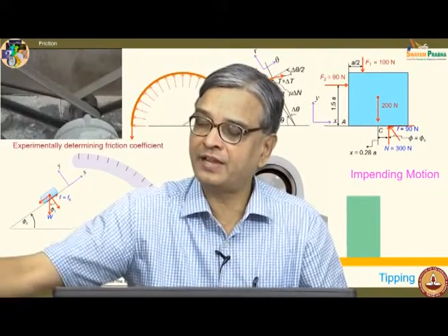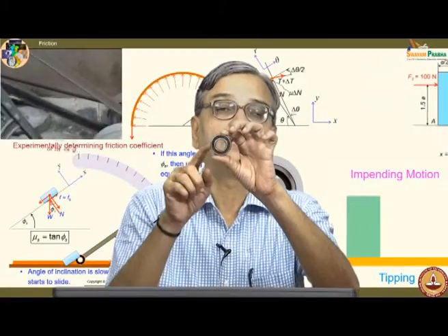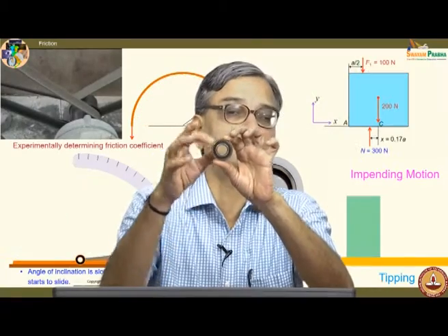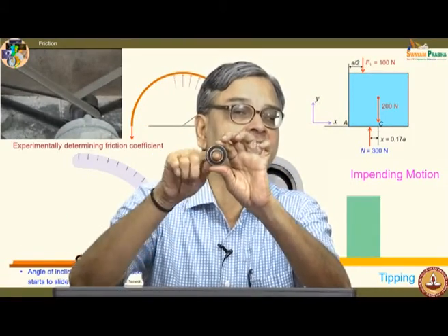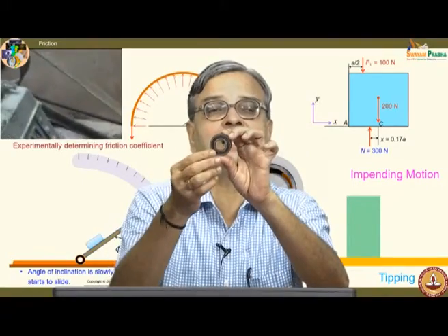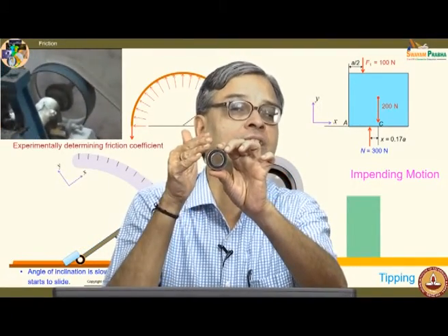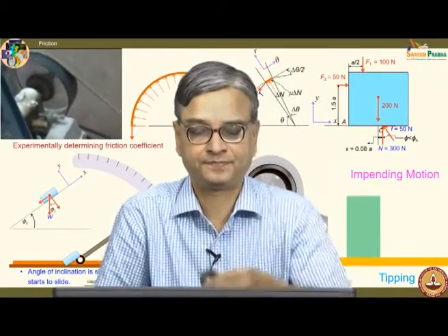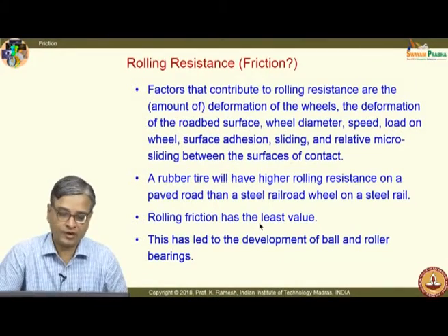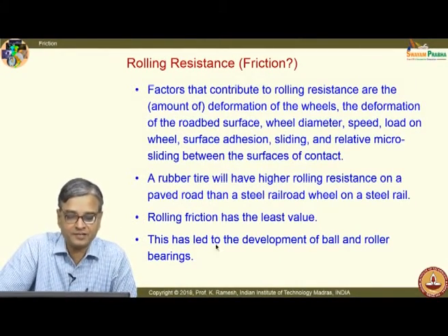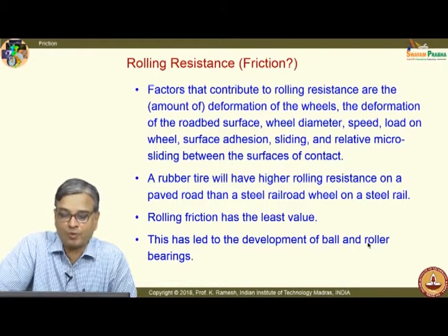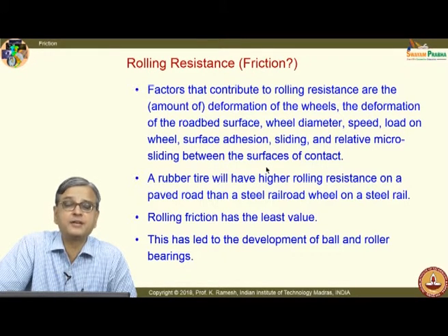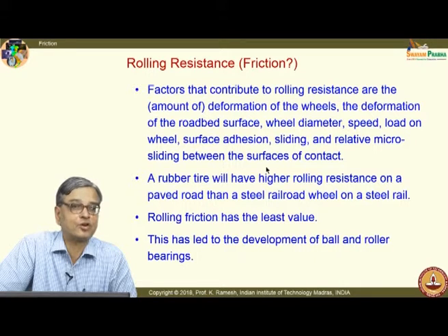And you also have, in important applications, the end points completely sealed. This is a ball bearing, you do not see the inner casing here. This is also required. You have many submersible applications where you do not want any fluid to get into it and affect its performance. So, you have this hermetically sealed. So, that is what is summarized here. Rolling friction, the motivation is, this has led to the development of ball and roller bearings, which are normally used in many engineering applications routinely.